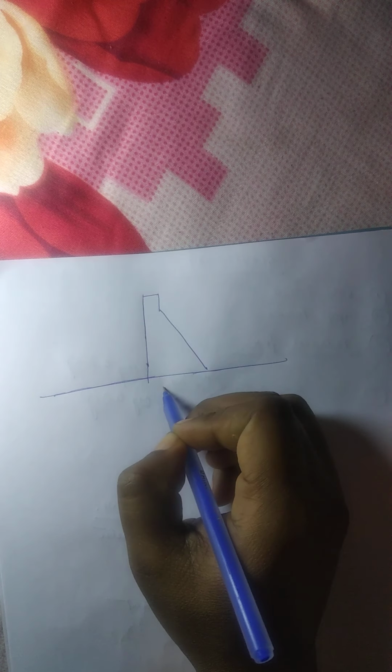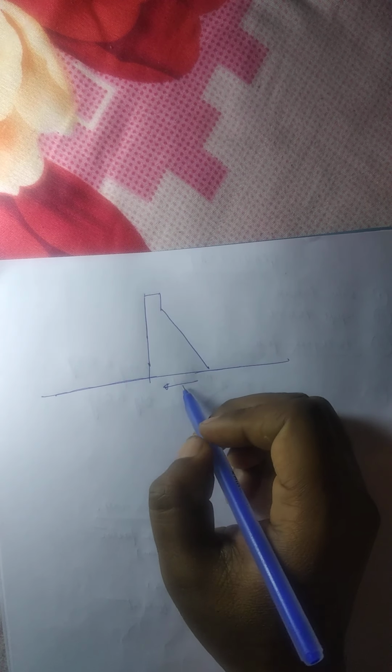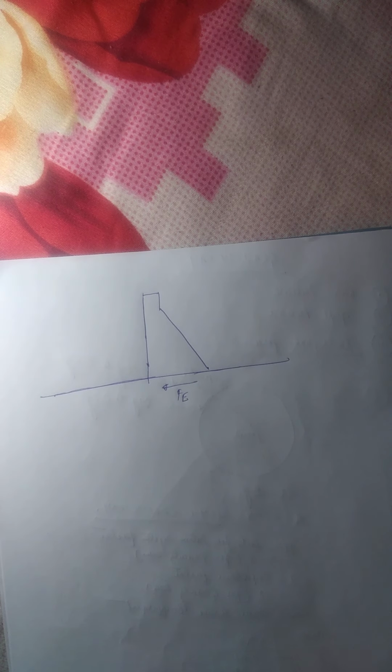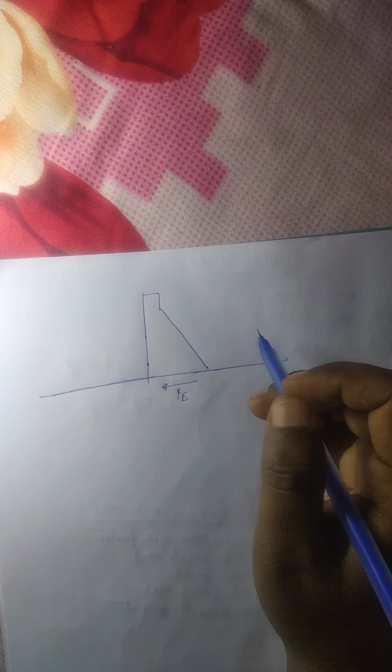This is the cross section of the dam, and here is the weight of the dam. Whenever the horizontal acceleration or horizontal force acts, suppose this acts in this direction, suppose this is Fe, the force in the earth due to the seismic force, and due to this force the body of the dam tries to dislocate in the opposite direction. That means the inertia force will act in the opposite direction of the force or shaking of the earth.